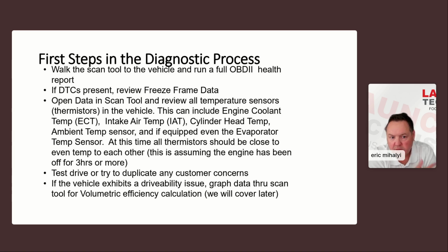If it goes high, right? Let's say it shorts out, and in the case of it shorting out, it reports high, 200 and something degrees. I've seen cars coming in misfiring, and guys are swapping coils, putting injectors in the car. They're chasing this misfire, and what the car is doing is actually the computer compensating. They think the car is overheating, so it's doing that cylinder deactivation, right? And it's shutting the engine down.